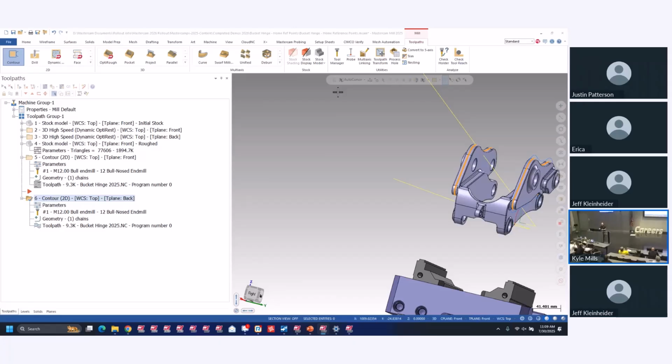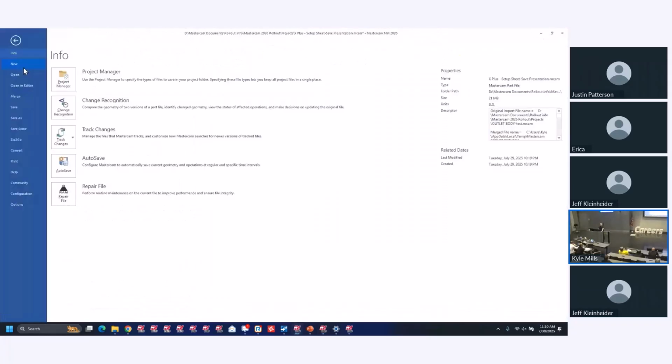But what I've noticed with doing things like that on certain machines, some machines are better than others, is the more motion you have, the worse the final product is. So if you can eliminate axes, I know sometimes we need full 5, right? We need full 5 sometimes to get in spots. But if you can eliminate things from moving, you get a much better result. So that's what I like to do, and that's what I like to show you guys. So I'm going to open up a little bit of a part here. I just got some little parts here. Let's have some twists.